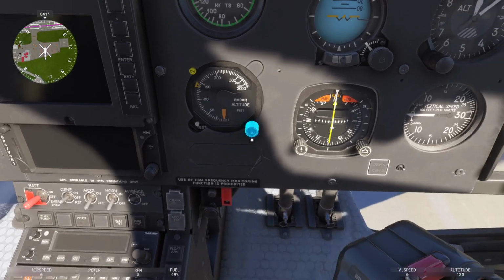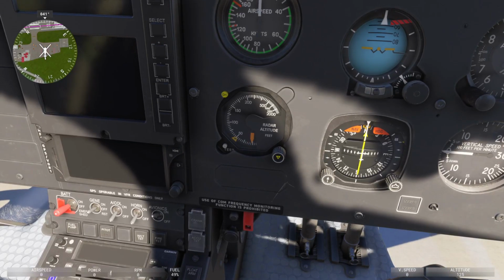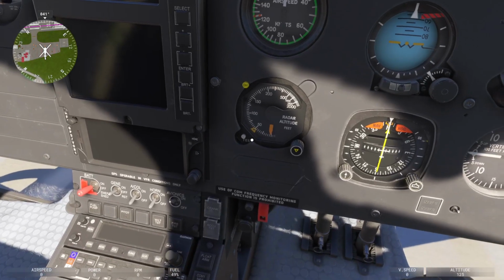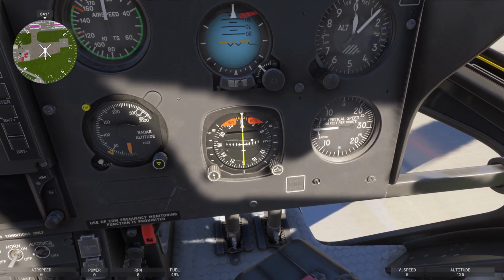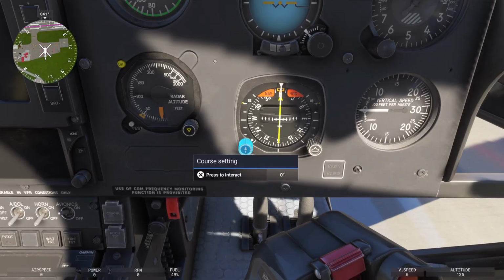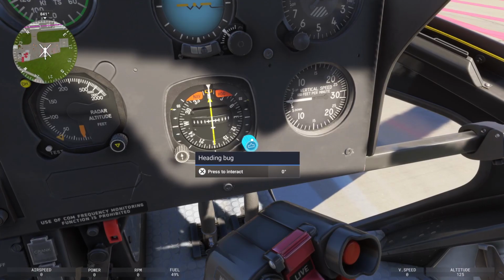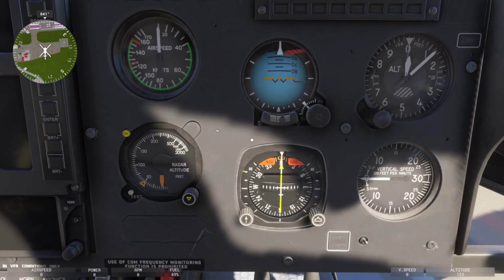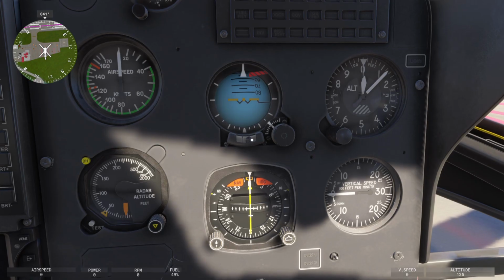So when I do the hoist missions I do quite regularly, I would set this at 50 feet, because that's the optimum height for the winch in on this. If it buzzed at me, I know that I'm dropping below 50 feet. Okay. And then you've got a test function here, which we'll use shortly. This here compass dial, you've probably seen it in quite a few of your helicopters now. Exactly the same. Enables you to set your course and your heading. Course and heading, two completely separate things. That's a different lesson in itself. That's going to be for navigation. We'll visit that another time.